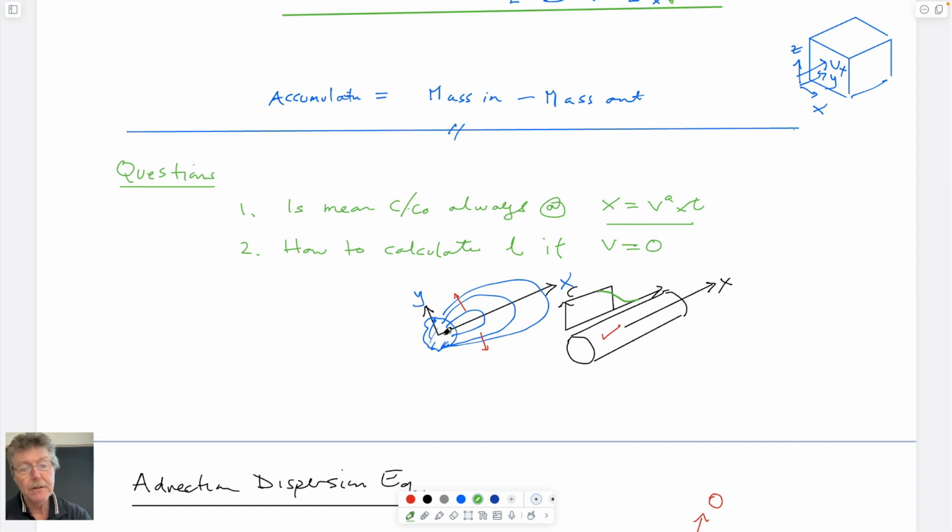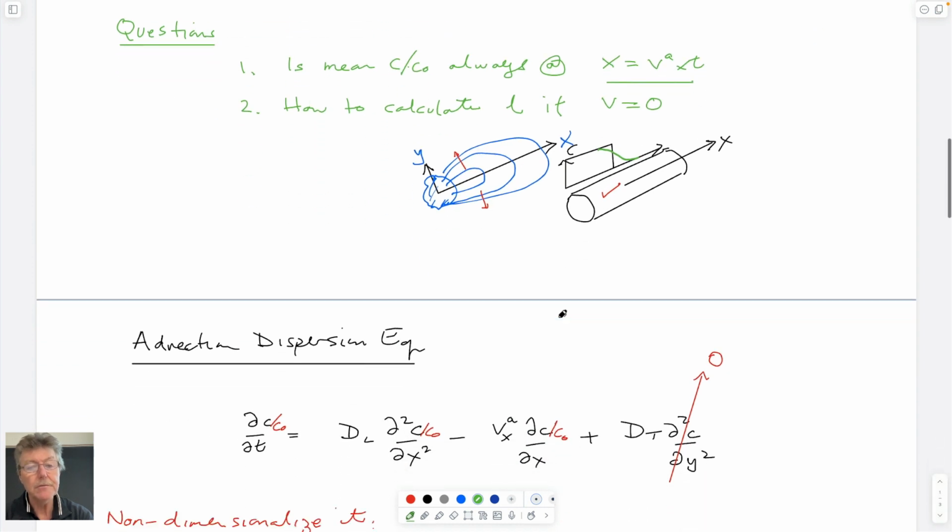You can imagine that if it goes downstream in a tube, then it's confined and perhaps it would keep that high concentration. But if it's allowed to spread laterally, because you have lateral gradients, dC/dy, then as the stuff moves out to the side, you have less material dissolved in water that's contained within this zone. And so you might expect that this peak amount might diminish.